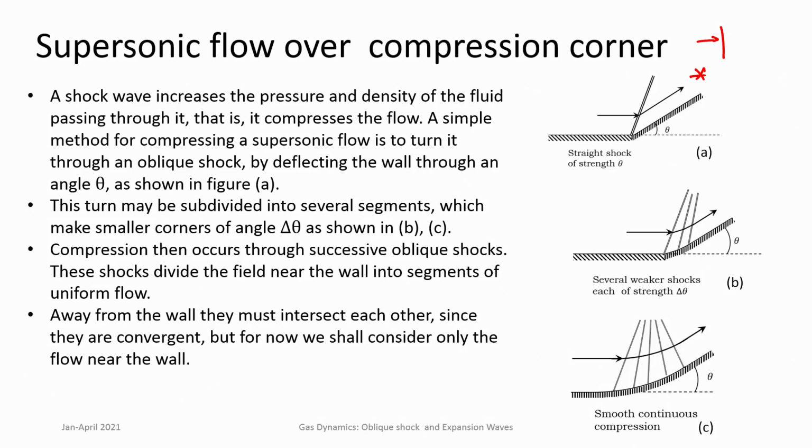Okay. Now, instead of considering such a sharp turn, the total turn through angle theta can be done through a set of small angle changes. At each small turn you have an oblique shock, but since each turn, the delta theta, is small, the shock wave strength is also small.